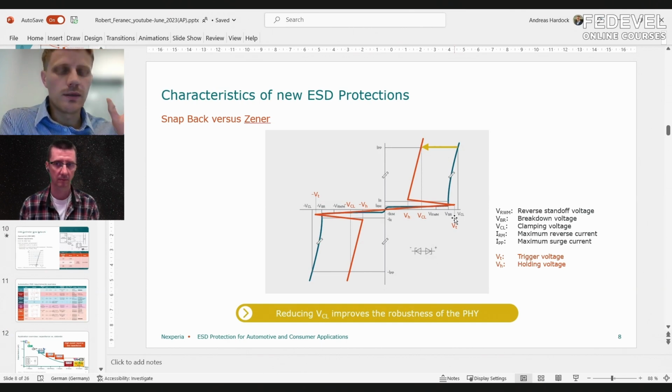This is not a classical inductor, it's a distributed inductance, but still it helps when it comes to overshoots of very short duration, a few nanoseconds. Those short overshoots can be at least a little damped by the natural inductance of the trace.